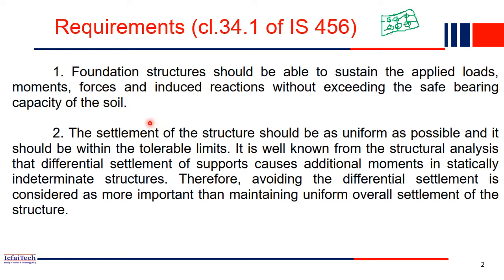The next thing we have to additionally take care of is the accurate estimation of all types of loads, moments, and forces needed for the present as well as the future expansion, if applicable. As I mentioned, the foundation is the first part we make and it is below the ground surface, right? In future, if you want to increase the floors, you cannot increase the foundation, because the foundation is made one time.